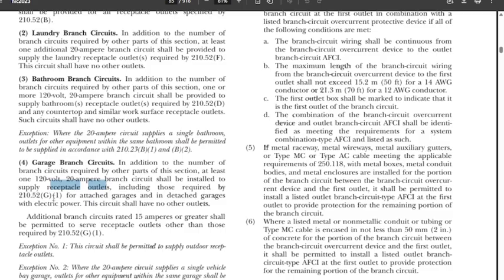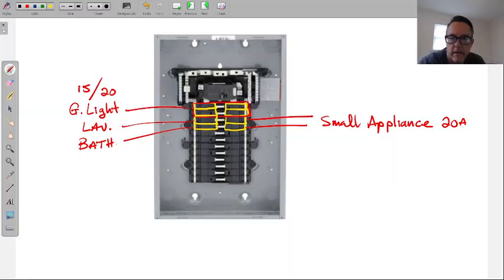All right, including those that are required, and we'll get to the ones that are required. Sorry, it has to do with whether or not the garage has power. Right? Some garages don't have power, and you just open the doors manually. If you have a garage with no power, then of course no circuits are required. All right, so again, another breaker here now represents, if you have one, a garage. All right, there's our garage.